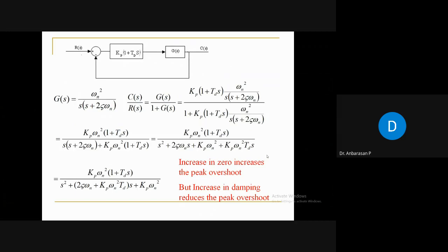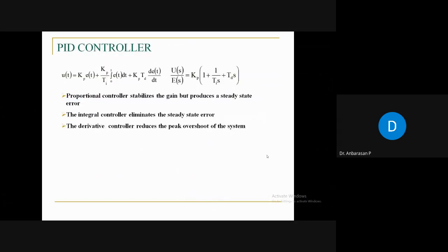We go for the proportional integral derivative controller next. This is a combination of all the three, that is proportional, integral and derivative action. It is clear from the above discussion that a suitable combination of proportional value, integral value, and derivative value can improve all the desired performance of the closed loop system. Also, the proportional integral derivative controller is widely accepted for industrial processes since it is a robust one. That's why it is widely used in industrial applications.